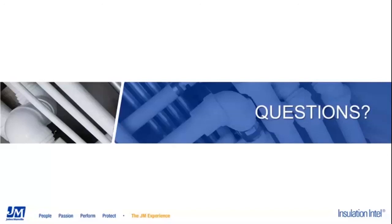All right. Thank you, John. The next question, I'm going to go ahead and hand this one to you, Meredith, and that is, what would you use for acoustical noise control in a dust control booth? In a dust control booth. So I would say that if you're looking for something that's going to provide acoustical performance, then a fiberglass board would be a great option.